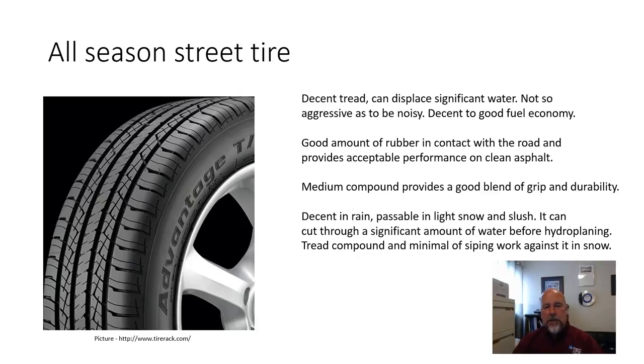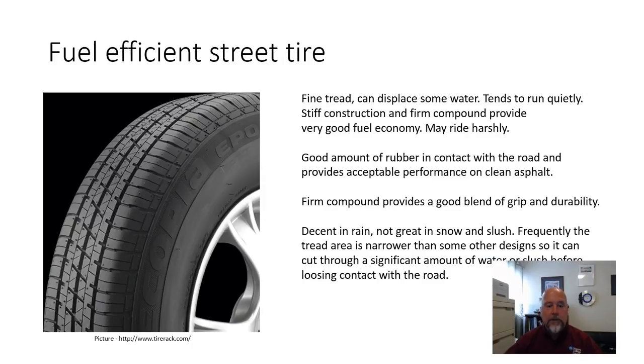People do use these for all four seasons, but in Canada, it's very common that you want to switch to snow tires. The tread is just not aggressive enough to handle any deep snow at all. And when I say deep, it's not uncommon to get 6 or 8 inches of snow, and this thing would have a problem with that. However, it works pretty well as a general all-around tire for the other three seasons of the year. If you're in an area that doesn't get much snow, you can get through the whole year with them without too much difficulty.